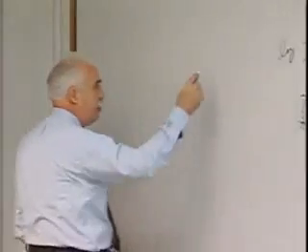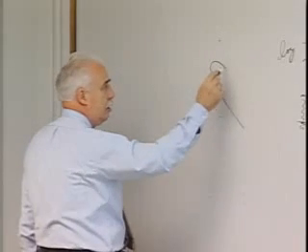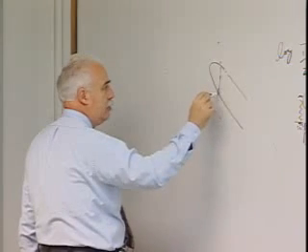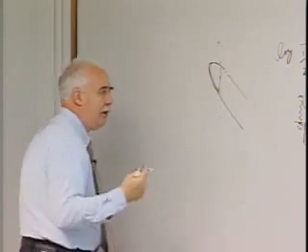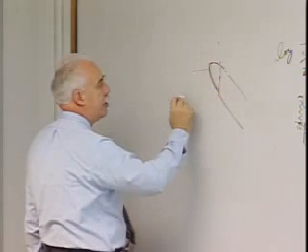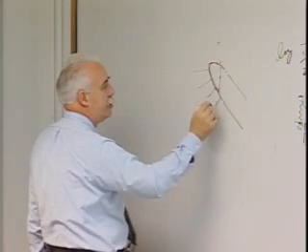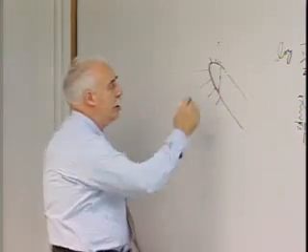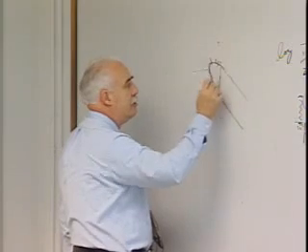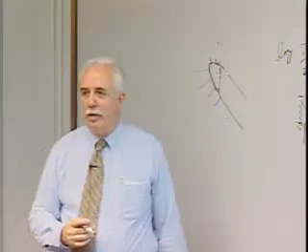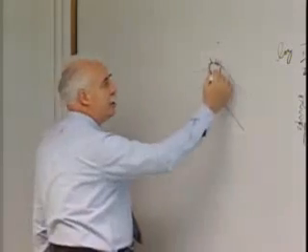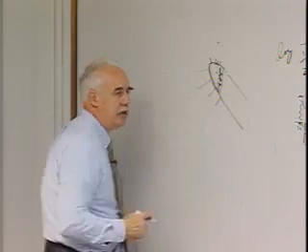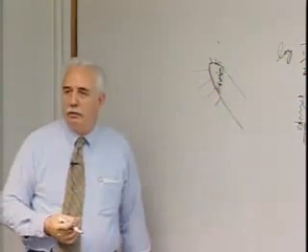Just picture a two-dimensional airfoil at angle of attack, and a carbon section, if you want, covers from here to here. Now if I look at the heating distribution, here the heating is quite high, still high over here, still high over here. Boy, it drops off very, very quickly over here. Well, if I can radiate this energy over here, this basically becomes a uniform temperature oven, first order. And the insulation is back here, I don't know how you illustrate insulation, to keep the lower temperature structure from getting too hot.